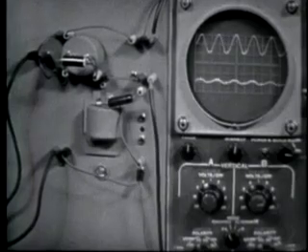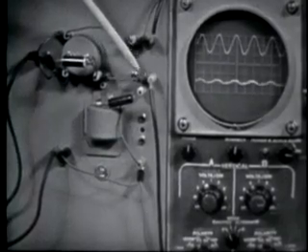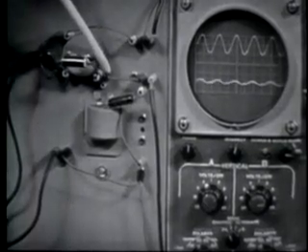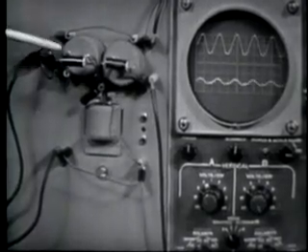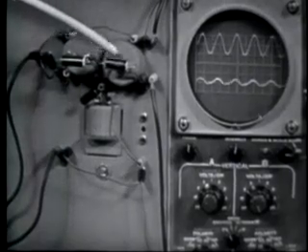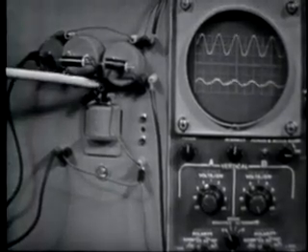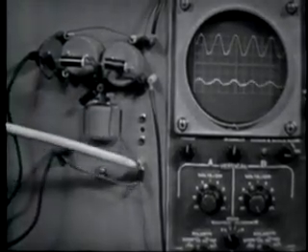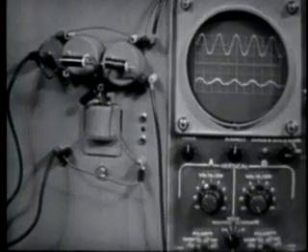frequency response. Now to make the T section we'll need another parallel tank in the output leg of the series position, and we'll need to move our series tank over to the junction between the 2 parallel tanks. Now let's do this. Okay, parallel tank here in the input series leg of the filter and a parallel tank in the output series leg of the filter. And our series tank now is connected from the junction of these 2 tanks down through the capacitor, the inductor in series, and down to ground. So we have a T section band reject filter.